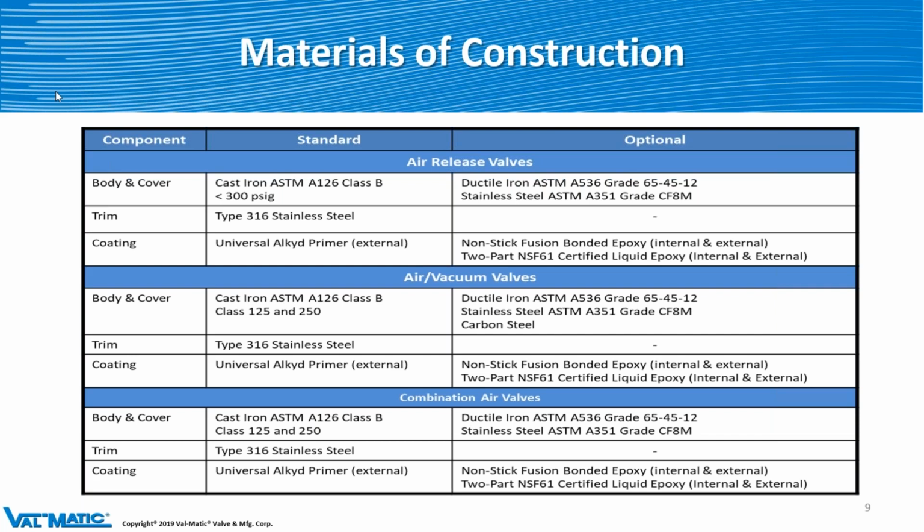As far as coatings, we can do epoxy, bonded epoxies, internal, external. We can do fusion bonded epoxy. So there's a lot of things we can do in case there might be chemicals or some other things going on with the media that's going through these air valves.